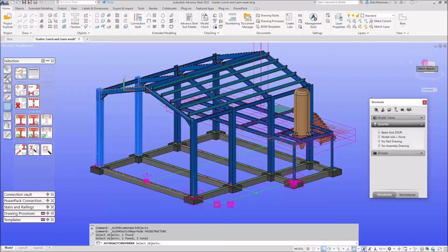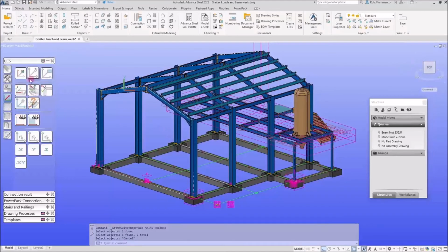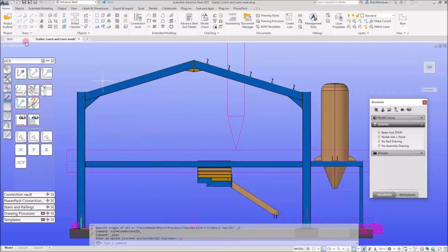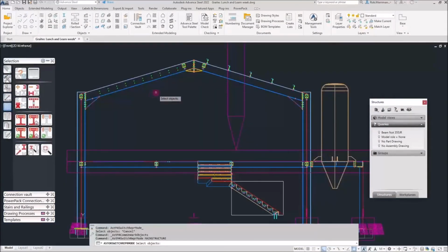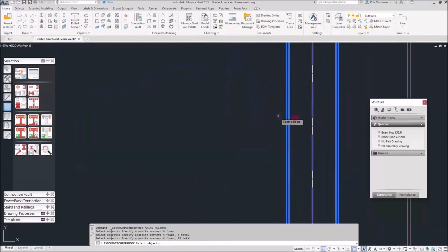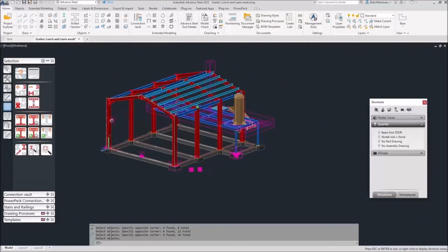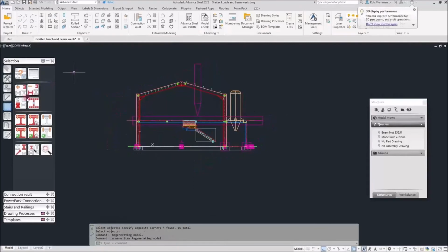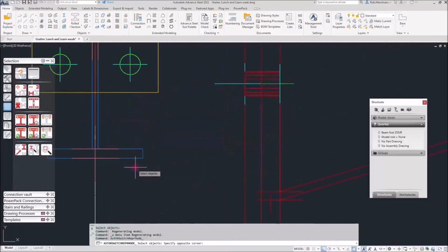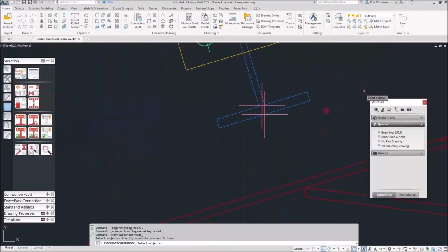And I'll tell you what we'll do. We'll set our UCS back to world. We will just do that. Go to a wireframe. Because what I can do is I can say select all the rafters, select all the columns, right click. That's marked everything. Oh, missed the tie beams. That's fine. We can add the tie beams to the marking, not a problem. Tie beams in here.